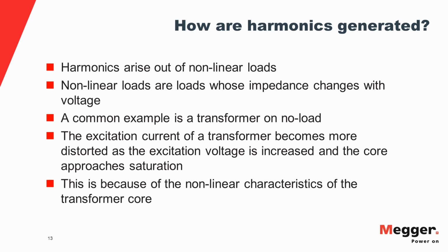The problem of harmonics is very recent, and that's because of increasing use of non-linear loads, or loads which draw current for only a portion of the voltage waveform. Transformers have been around for a long time, longer than electronic power converters. So the problem of harmonics has been around for a longer time, but it wasn't so prominent before the advent of electronic power converters or electronics.